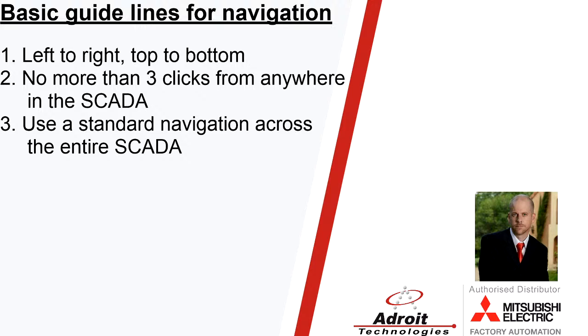it's not unfeasible for an SI, a system integrator, or an engineer to come in, design the SCADA, he moves on, and then somebody else has to come in, and they decide, well, that navigation's no good, and we'll decide our own, and the navigation changes. And this just puts more load on the operator at the end of the day. Remembering, guys, that the idea here is that we want to keep our interface as user-friendly as possible for our operator. It's also ease of use for the operator as well as for training of the operator again.